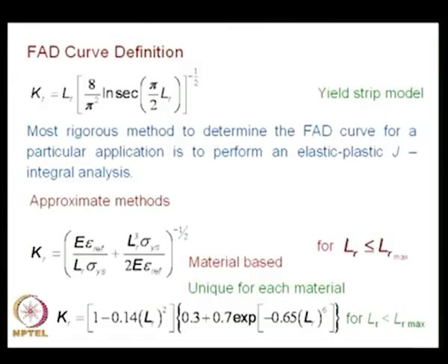See, the empirical approaches have found greater acceptance in applying fracture mechanics to actual structural components, because the problem domain is so complex. People have found by performing suitable experiments and collecting data, doing a curve fitting exercise is a lot more profitable, and that is seen in the FAD approach also. And to refine the analysis, the KR and LR definitions are suitably taken.